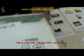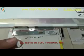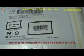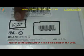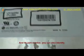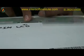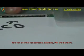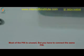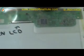This is an old LCD with the CCFL connection. You can see the CCFL connections here. You can see the part number. It is indicated in bold, 15.4 wide. You can also identify it. It has a connection like this. You can see the connections. There will be pins, and it is a 30 pin connection. Most of the pins are unused, but we have to connect the same pins.